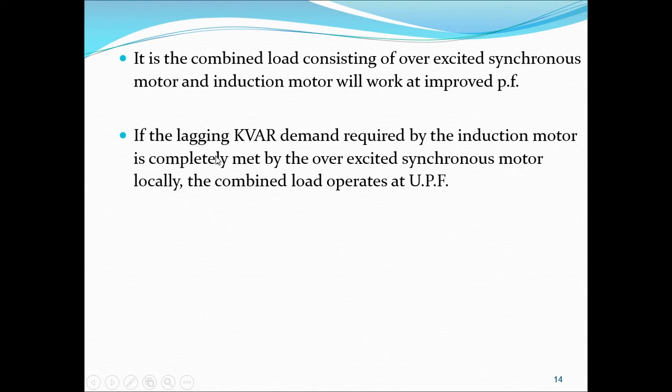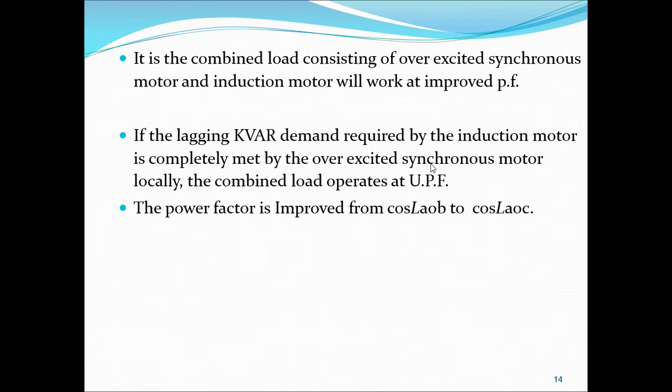So if the lagging kVAR demand required by the induction motor is completely met by the overexcited synchronous motor, then the combined load operates at unity power factor. That is, the power factor is improved.